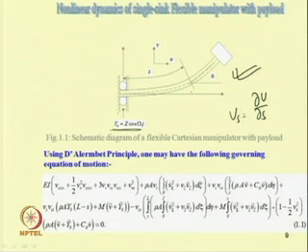So, the transverse deflection of the beam, if it is V, then V_s is ∂V/∂s and V_ss equals ∂²V/∂s². If one takes this as a simple Euler-Bernoulli beam, then the equation will contain only the first term, that is EI ∂⁴V/∂s⁴, but due to taking moderately large